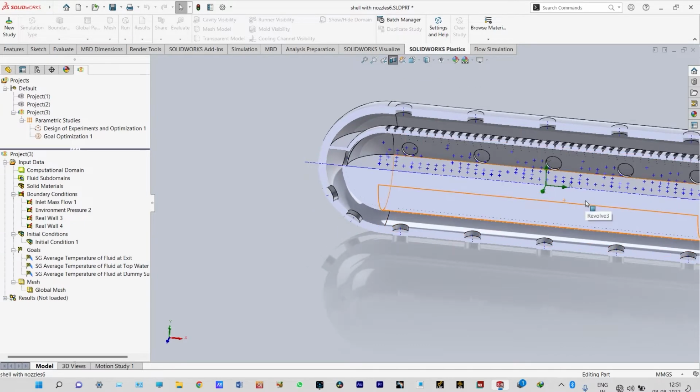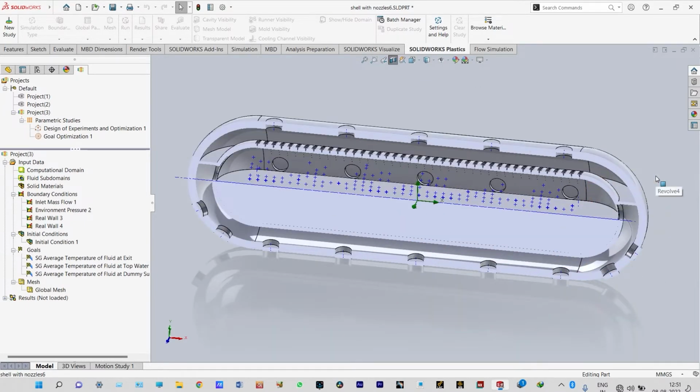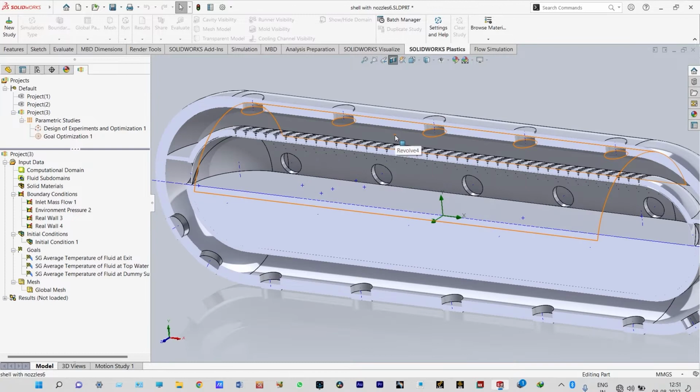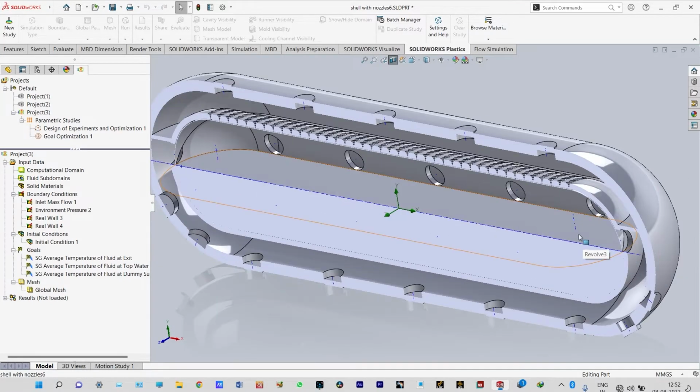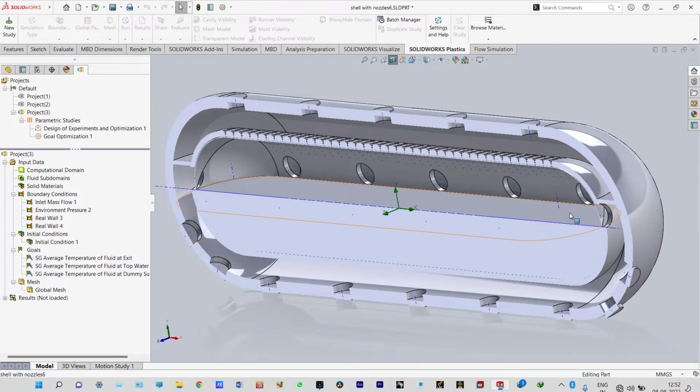In this case our aim is not only to have an analysis, but at the same time to go for some kind of parametric study and also optimization. Optimization means getting the water temperature at the exit level as per our requirement. We have a single fluid domain, and in a single fluid domain two heterogeneous fluids cannot be mixed, so we are utilizing a special method known as the free surface technique using SolidWorks Flow Simulation, right? So without wasting time, let us start our simulation.